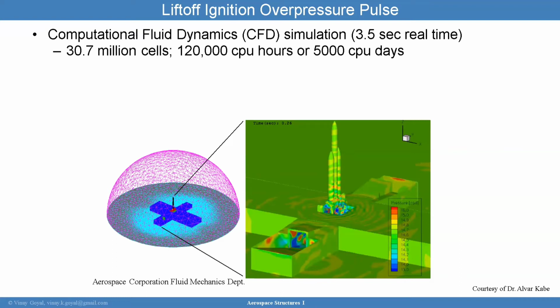Another thing I want to point out is that you begin the simulation a little bit early, at t minus 3 seconds, say, and at this time you're going to have the engine chamber pressure slowly increasing. Then at about t minus 2.5 seconds, during this period the chamber pressure usually rises very, very rapidly, and the nozzle becomes fully choked.